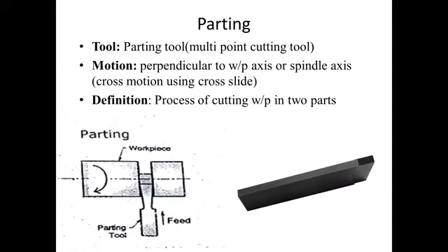Parting operation. Parting is similar to grooving, where again we have a multi-point cutting tool for the parting operation. The motion again here is perpendicular to the spindle axis and it's given by using the cross slide. The definition of parting is cutting the workpiece in two parts.